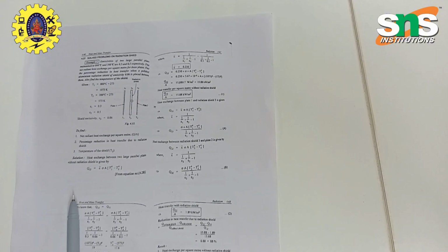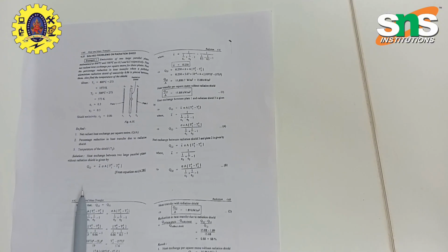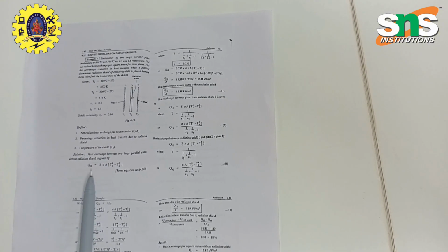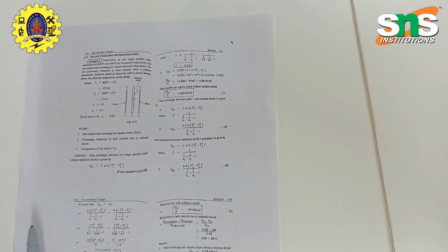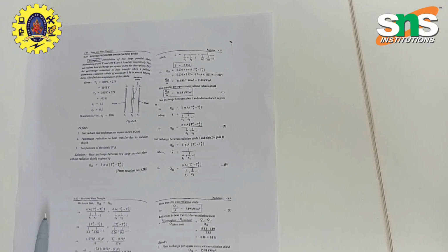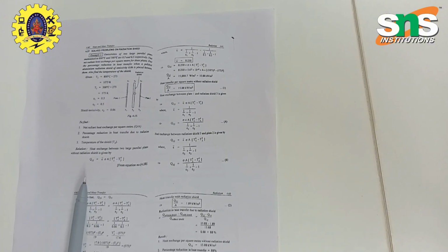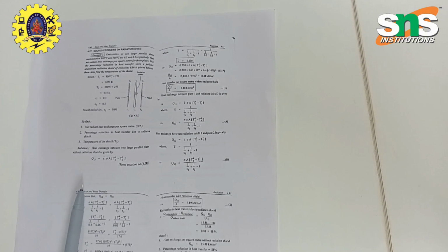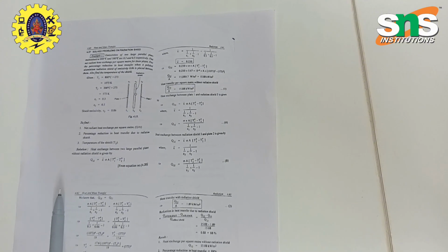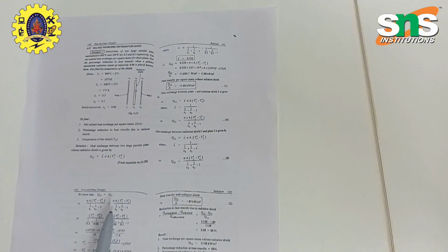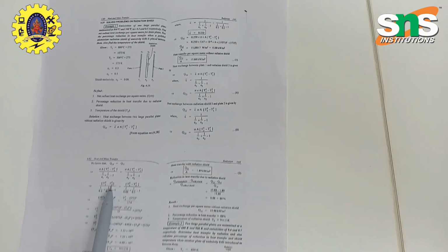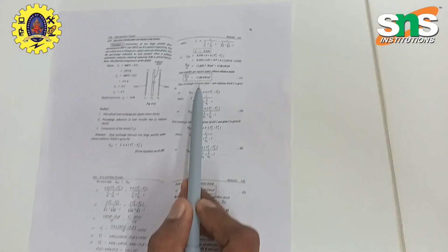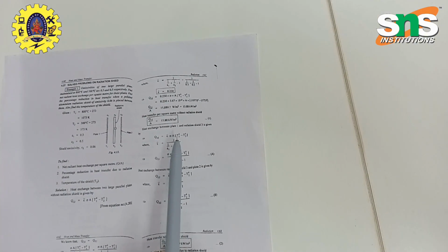First, in the solution part, from the data book we write the parallel plate heat transfer equation with emissivity: Q is equal to epsilon bar sigma A (T1 to the power 4 minus T2 to the power 4). Substituting all values for plates 1 to 2 into the emissivity expression, we get a value of 15.88 watt per meter square.